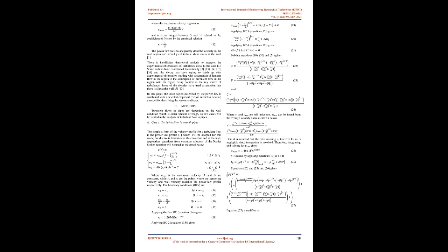The wall shear stress, if not measured directly, for example by the new micropillar shear stress sensor, can be found by using pressure sensors and the equation. It influences the wall shear stress and energy, as eddies develop in the viscous sublayer and flow out to the other regions. Understanding the viscous sublayer may also be the key to understanding how drag reduction agents work. Where dP/dx is the pressure gradient.